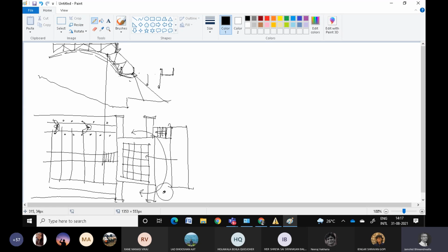And more important of all, you will have to decide how you have suspended your catwalk, from the roof, how the catwalk works. And what height you want to have above the stage area is completely in your purview. So this can all merge at that height that is there. And then from this height, you may have another beam, and this area may limit people coming in, and this kind of a cross section works like that. So this plan, the reflected false ceiling plan along with the catwalk, is one thing that is expected from you along with a good roof plan.